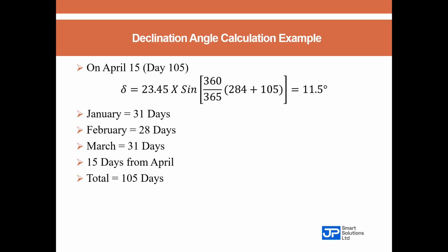During winter, we have the reverse because the declination angle becomes negative 23.45 degrees. So it means that we have lower solar hours, which produces the lowest output power, because we said that during winter, the area of the earth's surface receiving the sun rays will be smaller than the area that is dark. So this is basically how to get the declination angle while carrying out your solar PV system design.